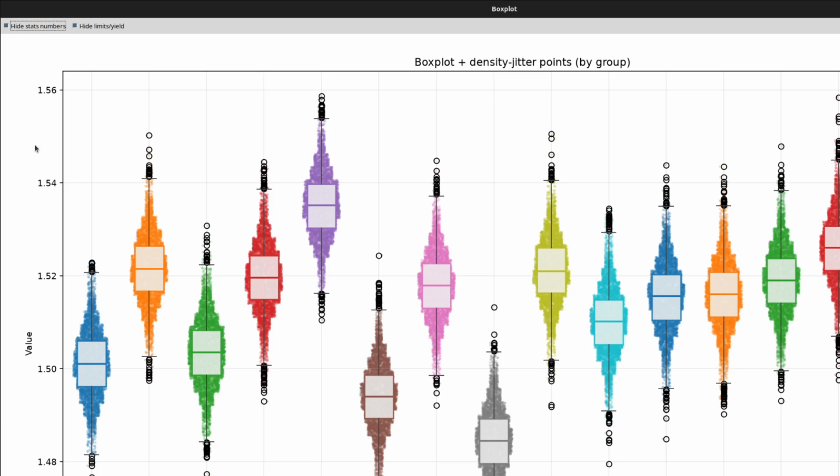Not on the kinds of parts that I deal with. This is about right where we've got a shift of 0.03 or 0.02 between a bunch of these cavities. So there's not a way that we're going to go shim these parts so that they're lined up. And these dimensions are in millimeters. So this is a thou difference between each of these median points.